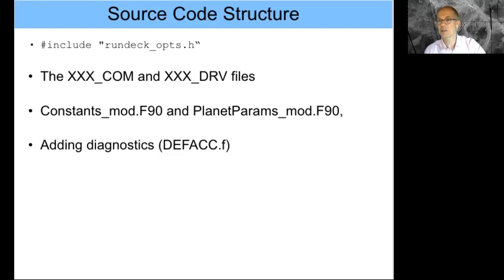That goes back also to this KRSF command that Costas mentioned. It's the same kind of principle there. You write out these checkpoint restart files, these RSF files, according to what you think you might need, because you might want to restart the model for another run at a different point as the model is reaching equilibrium, for example. Some people set this KRSF to be, say, 100 model years or 10 model years. It just depends on what your needs are. So think about what you want to do and how often you might want to write that file out.